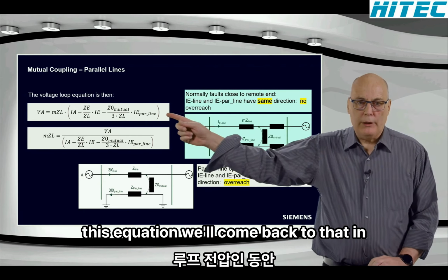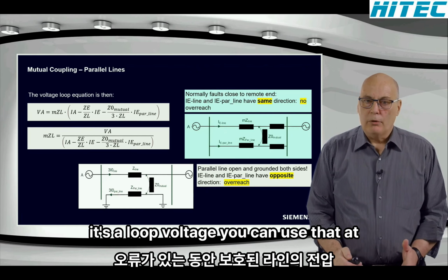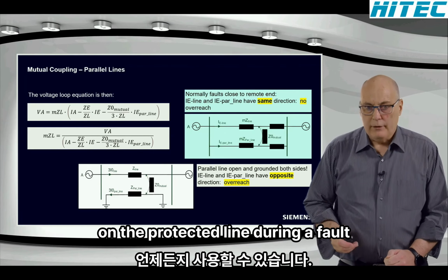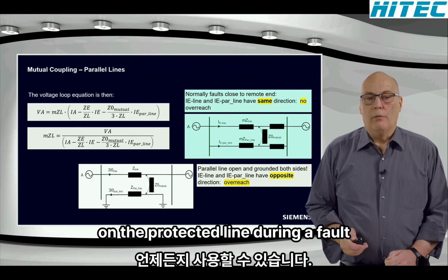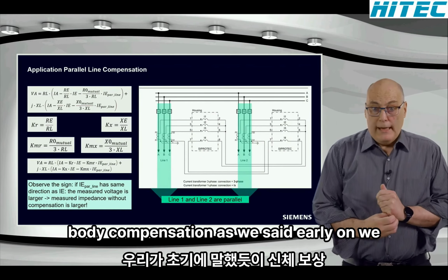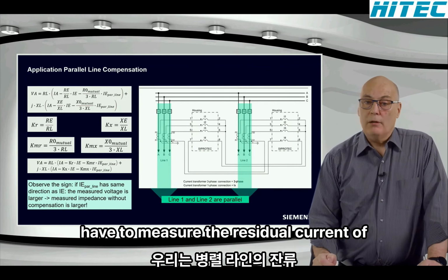Interesting, if you look at this equation, we'll come back to that in a little while. It's a loop voltage. You can use that at any time to calculate the voltage drop on the protected line during a fault with a parallel line coupling. For the compensation, as we said early on, we have to measure the residual current of the parallel line.